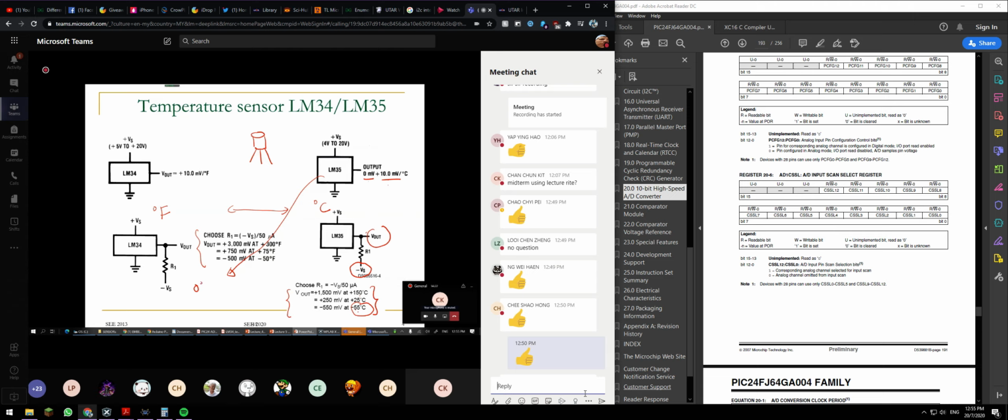Let's say this is 0 Celsius until, let's say, example, my 0 Celsius until maximum 150 Celsius. You're not going to directly convert it to become 0, 0, 0, 0, 0. This will become 1, 1, 1, 1, 1, 1, 1, means 0 volt, 3.3 volt. Am I right? So this is not a good design. Why? Are you sure in your application you need to measure negative 50 Celsius, negative 150 Celsius? So hot. If this is applied in the farm, your farm is melted already, correct or not? So you ask yourself, what is the correct output, if this is applied in your farm?